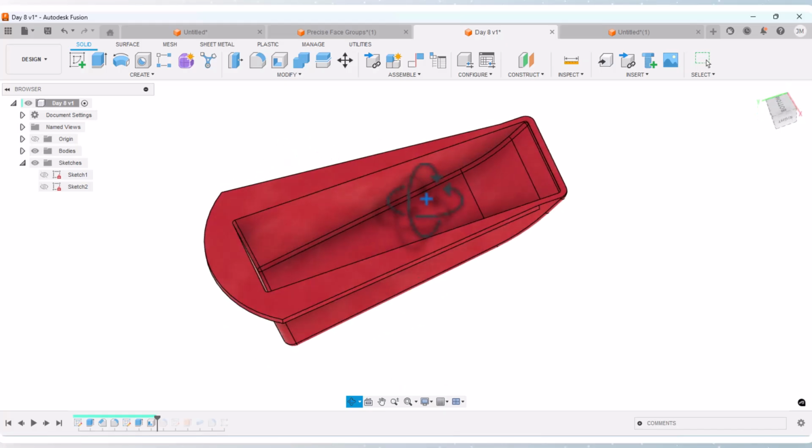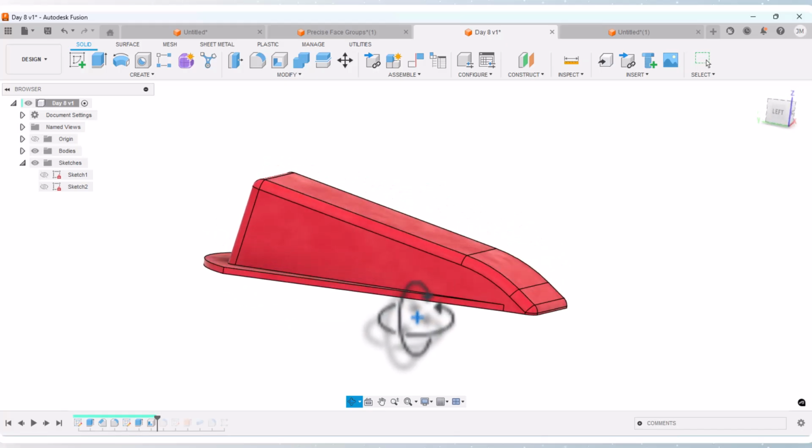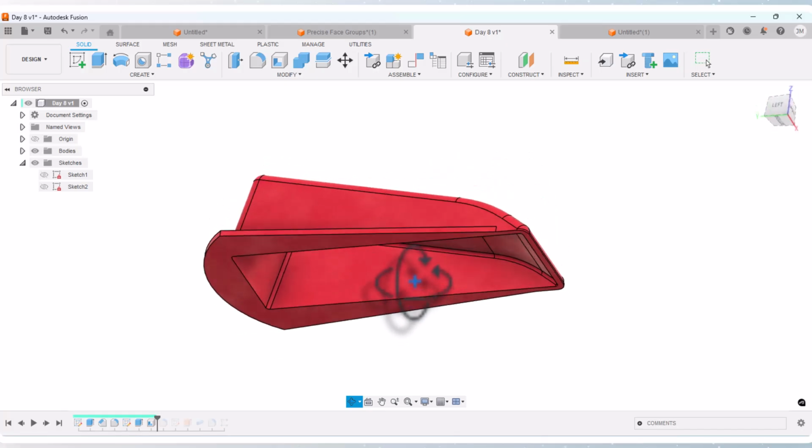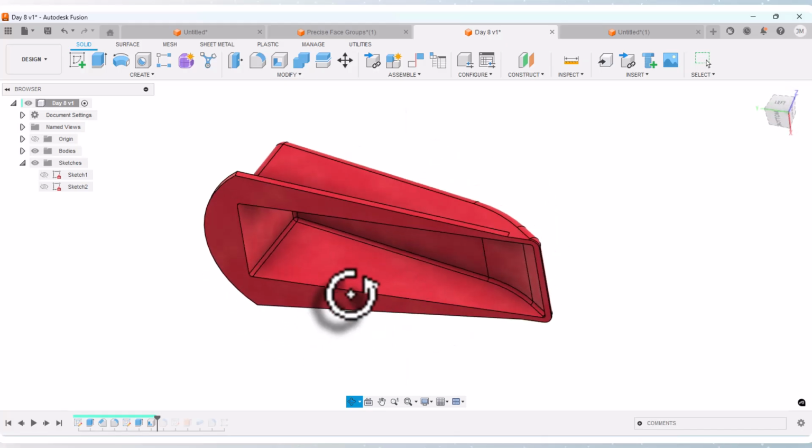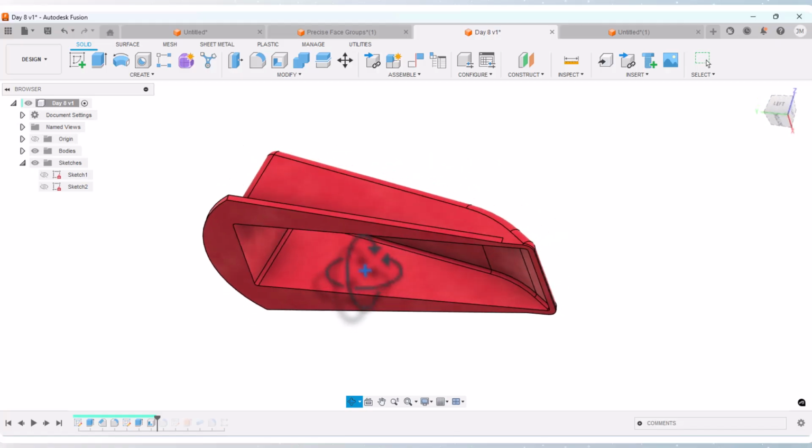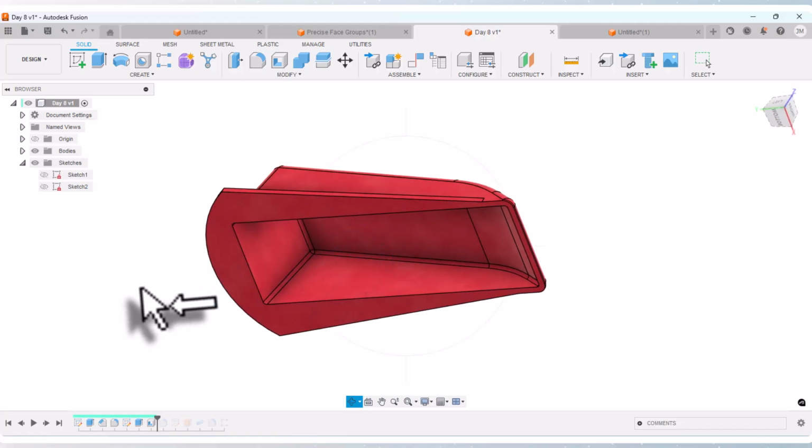And when you mold a part, generally you want it to be a uniform thickness. If you have thick and thin areas, the thicker areas will give you something called a sink, or an area where the material shrinks. It's all going to shrink after it cools off, but if it's a thicker area, it'll shrink more than a thinner area. So ideally, it's all the same thickness. And let's see what that shell thickness is.